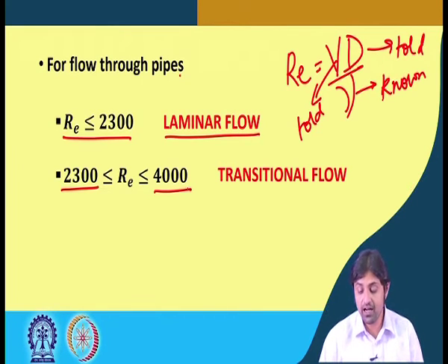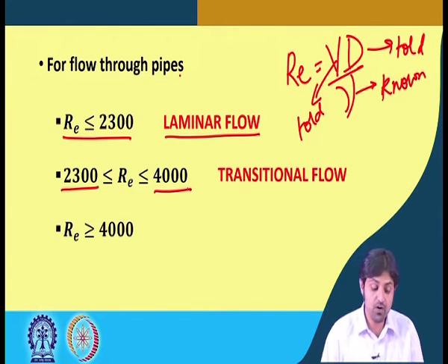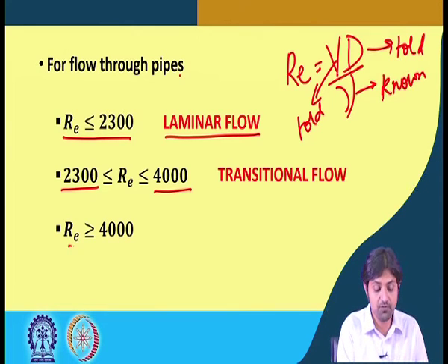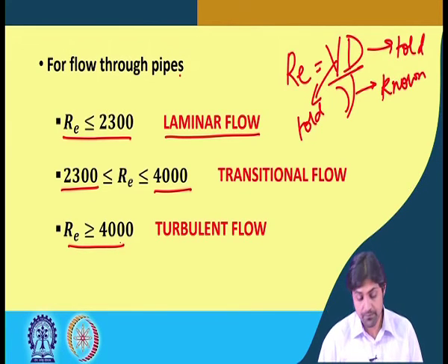So, there is one other category of flow apart from laminar and turbulent called transitional flow, which means that the laminar regime has just ended and the fully turbulent regime has not yet started. Some of the flow could still have some laminar properties and some turbulent. But when the Reynolds number goes over and above 4000 for pipe flow, the flow becomes fully turbulent.